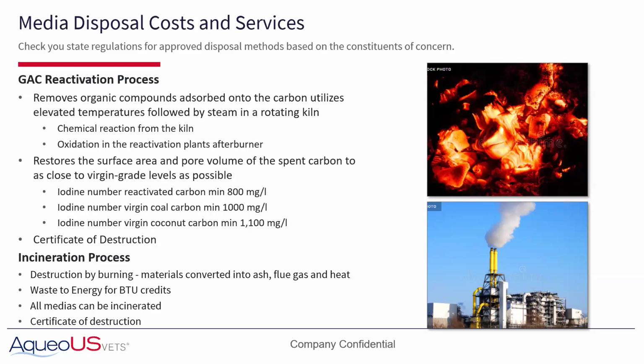And then that carbon is put back in that exact same system in order for it to be used as potable. There is reuse of the material, it is being reactivated and used in wastewater applications in some cases, so it's not going back for potable. The advantage here is you get a certificate of destruction. So the end user will not have something that's going to be on their books for years. Basically these compounds are destroyed so that you won't have a waste issue 10 years down the road.